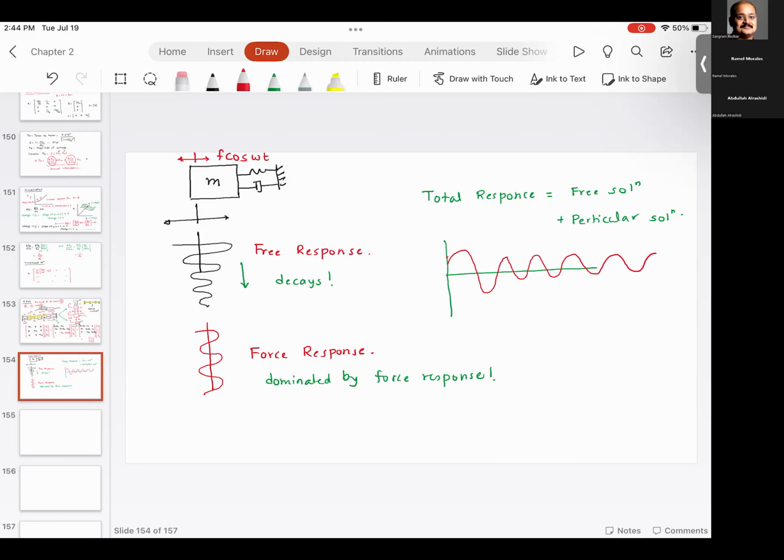So basically you have something called the state transition matrix that relates the old state with the next state, and you convolve, which is essentially you multiply and integrate that with the forcing, and that will give you the total solution of the system.